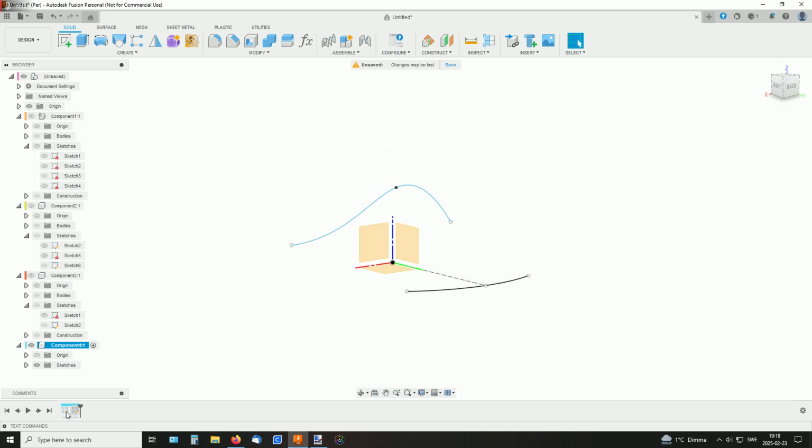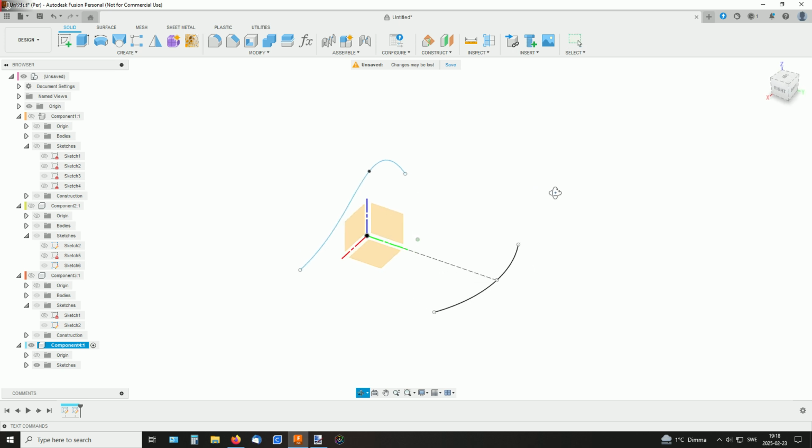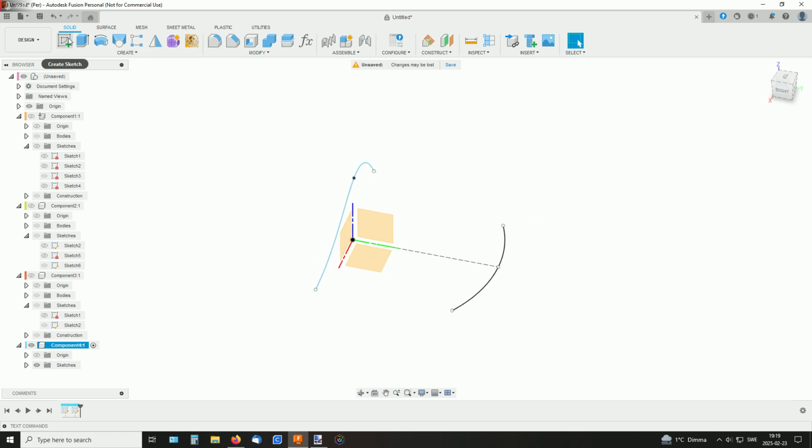They are two different sketches. And I want a curve that goes between them, where they would intersect. If this was extruded this way, and this was extruded perpendicular to its plane, where would they meet? Show me a curve there, please, is what this command says.